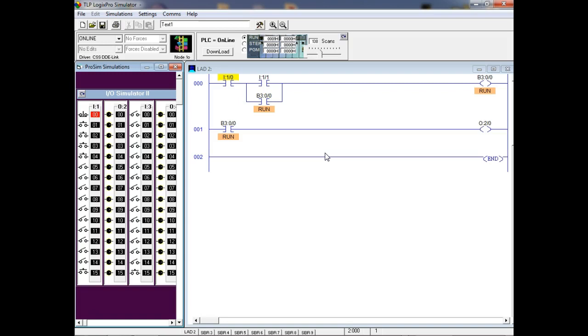And from then on, guys, just about every other push button that you'll run into in a PLC circuit is going to be a normally open button. And you just call it what you want it to act like, right? If you want it to act like a normally closed button, then use an examine if open. The only time you really are concerned is when you set up this stop circuit.